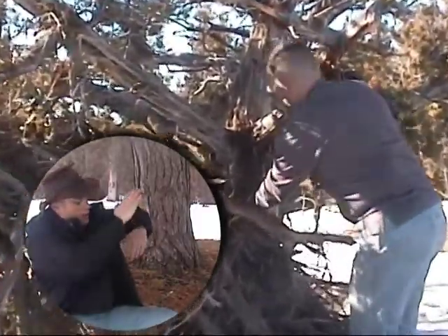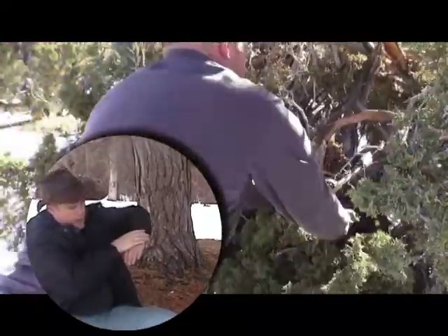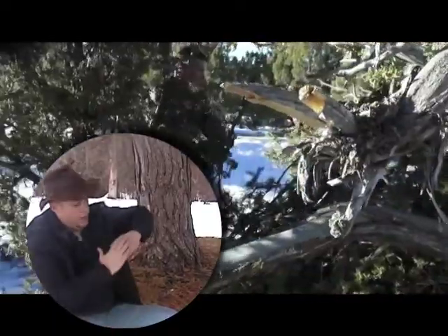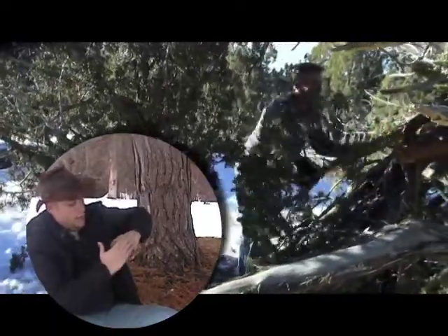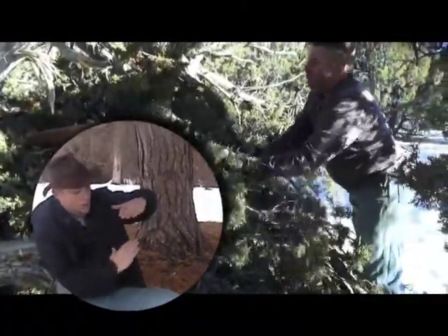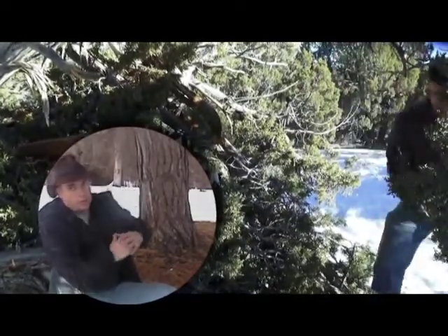That way when water or any type of precipitation lands on the shelter, it lands on the top shingle and rolls down and off, instead of the opposite way where it would land this way and then roll between the shingles and into the shelter. So always start from the bottom and then lay the next one up on top, going up the shelter.